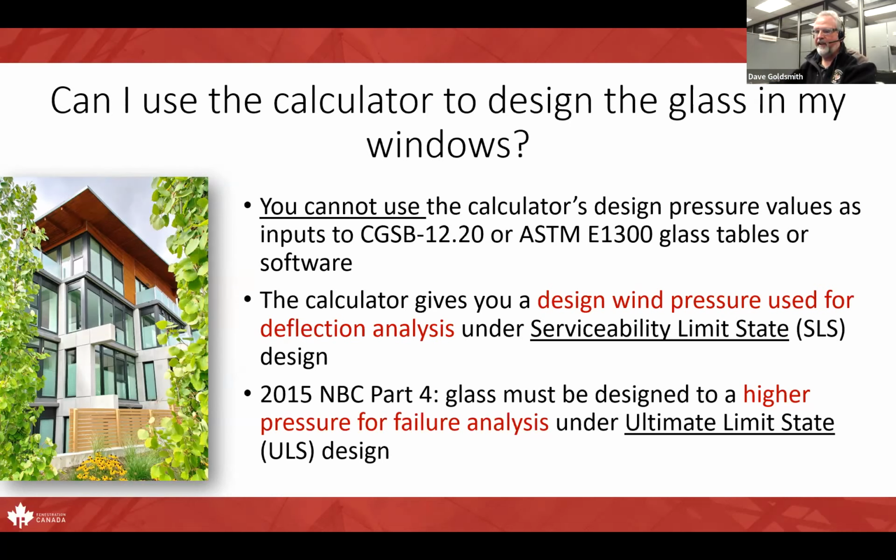And we have encountered this on a number of occasions on Vancouver Island. And it's because most manufacturers that are mainland based or Alberta based, such as in our case, are using glass area versus thickness tables that are based on climatic data that is like, say, 2/3 of what you would get on Vancouver Island. Right. In other words, if your default glass values are designed for a less extreme climate than the coast, then you may run into deflection issues on the coast.